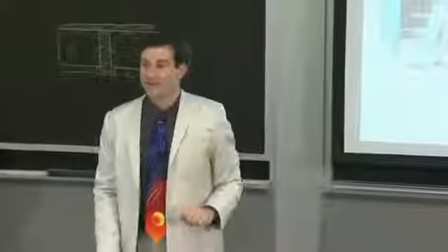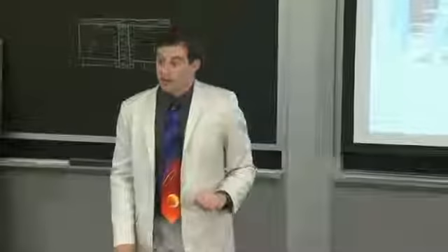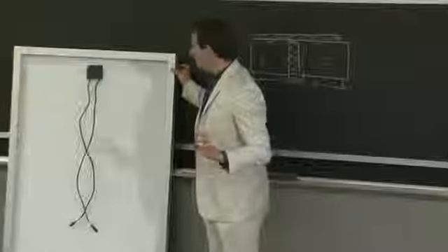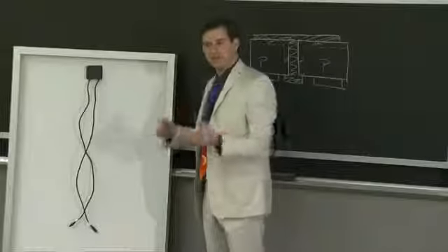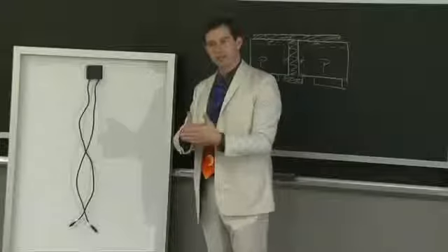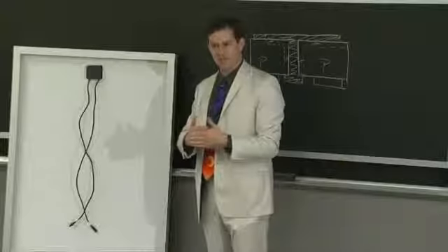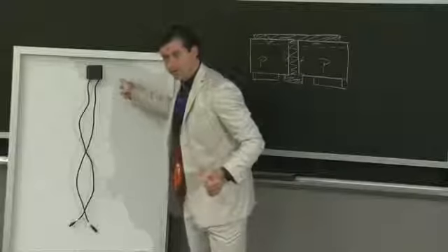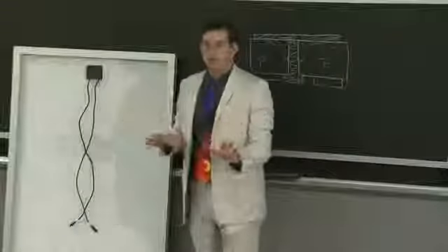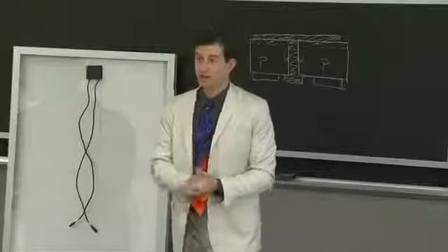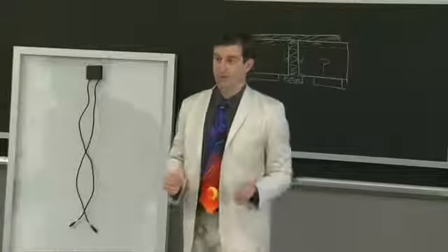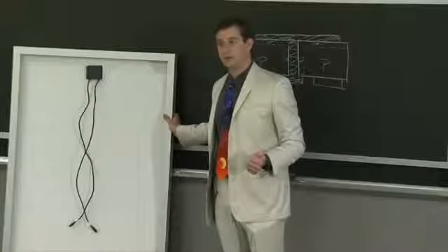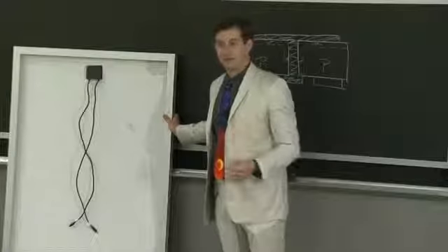What is the failure mode of degradation by water? By water, yes. So water, humidity. Typically what happens is in the laminate itself, there will be some part at the edge that water can get in. Not always, but in the poorly designed ones, yes. And so the water can get in and begin diffusing into the module. So if you have a thin film material that reacts with water, you might degrade the actual absorber layer itself. If you have a silicon device, the water could react with the metal and cause it to corrode, in other words, cause it to oxidize.